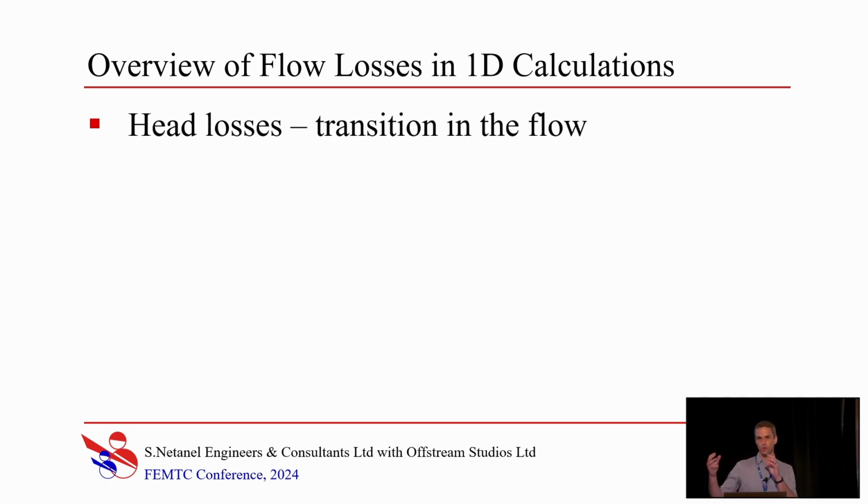For example, when flow transitions from a tunnel to a station, some pressure will be lost, and that would be represented by a coefficient that I would define at the node representing that transition. So in a series of tunnels and stations, I would have many transitions, many coefficients, but for the calculation, it would be the same if I summed up those coefficients, I would get the same pressure loss. So I could do with fewer nodes, which brings us to ducts.